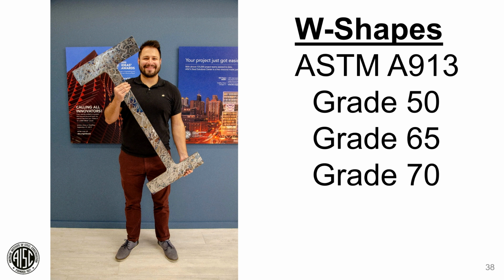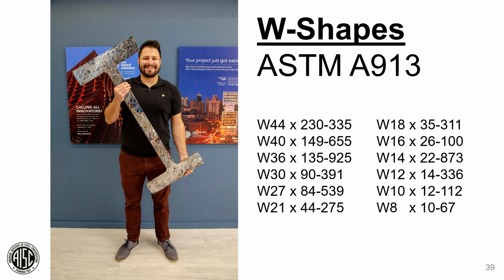ASTM A913 is most commonly available in 3 different grades: grade 50, grade 65, and grade 70. Also, quite a few shapes are available in A913. You can see we started at W44 by 335. We even have a W36 by 925 on there, but it also goes as small as a W8 by 10. This reflects information that we received from ArcelorMittal, Nucor Yamato Steel, Gerdau, and Steel Dynamics.